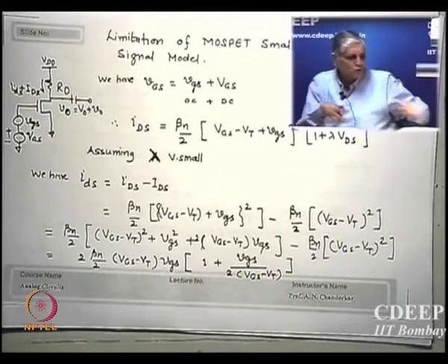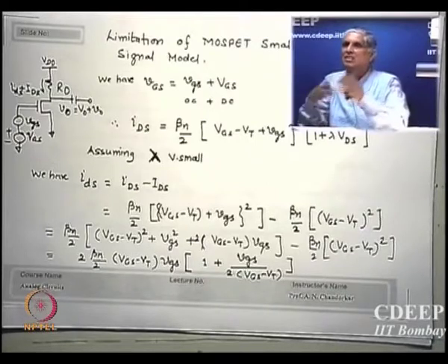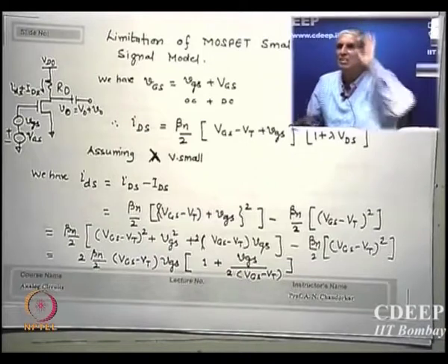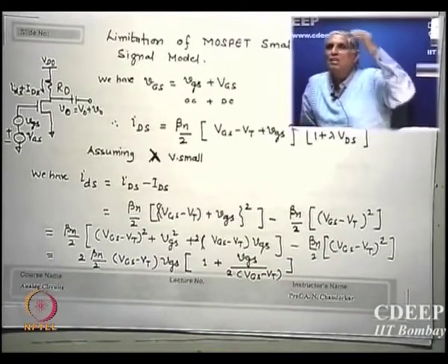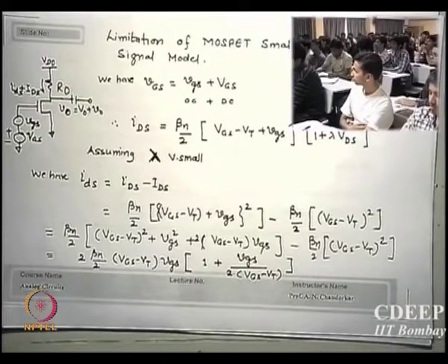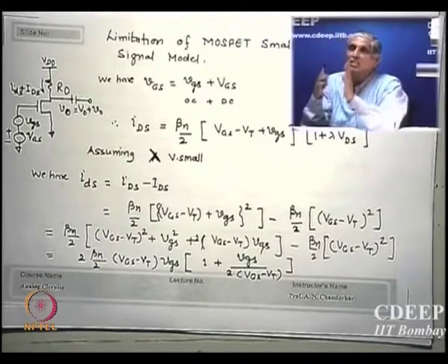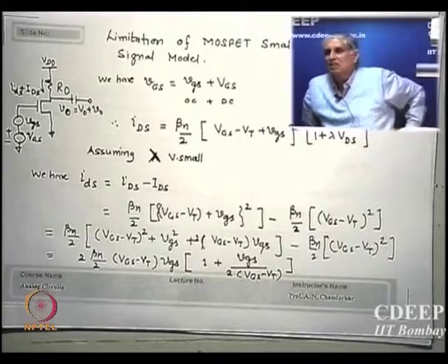What you are saying is true, this expression is non-linear. So to make it linear, I said the condition I can have is 2 VGS minus VT should be an order higher than the small VGS, and then I say it's linearized. Because all the time I say these circuits are called linear circuits, so I want to linearize it faster, okay. So I say what condition I can linearize, so I say okay, if I use this I am linearizing, is that okay?